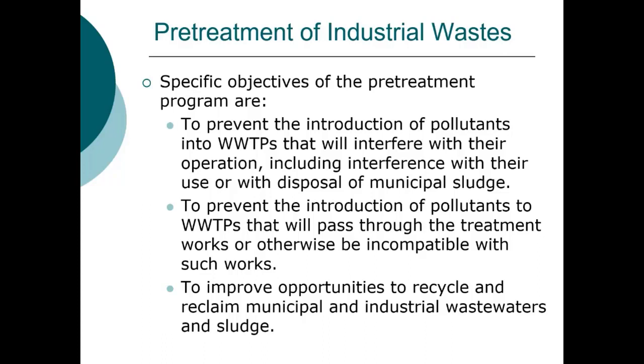If that effluent is discharged to the municipal treatment plant, that PFAS can end up in the biosolids, and that has a significant impact on what can be done with that biosolids, how they can dispose of it, whether they can land apply it, because we worry about the accumulation of those PFAS chemicals in the plants that are grown on the land where the biosolids are applied. So we have these really strict rules.